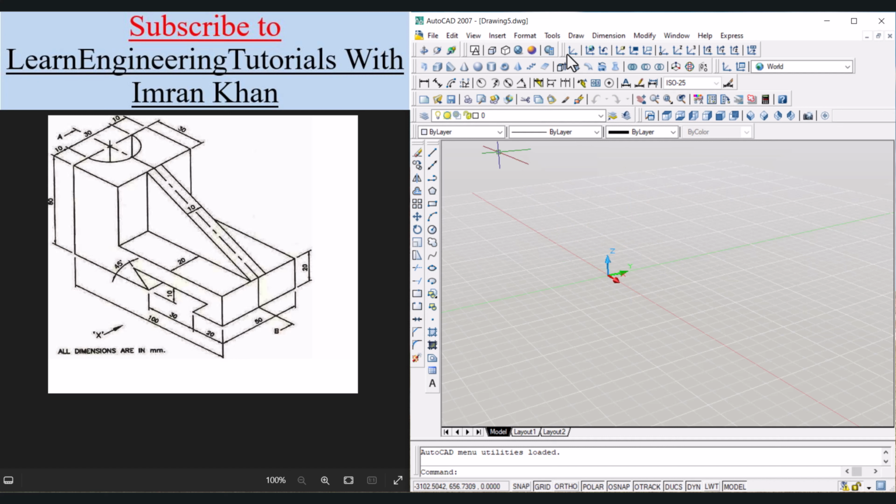Now we have brought some icons in front of us. So these are the UCS icons, these are the visual style icons, these are the orbit icons, these are modeling commands, that means 3D commands, these are the dimensions icons, these are standard icons. We can use pan or we can remove or copy objects from here. This is the layer menu, and these are the view icons. And lastly we have added these property icons as well, or property menu. On this side we have modify commands and draw commands.